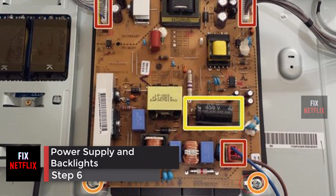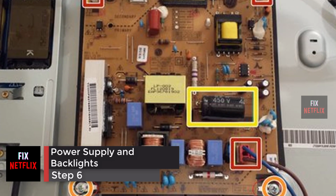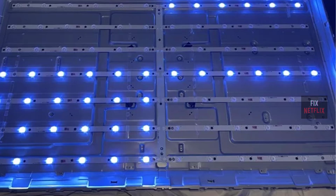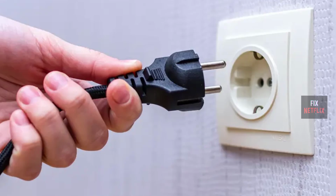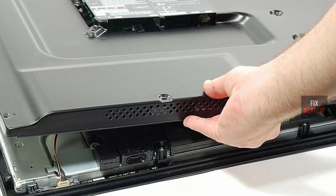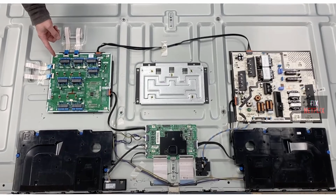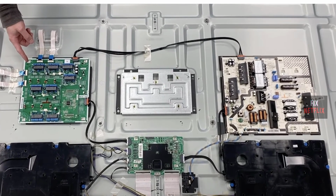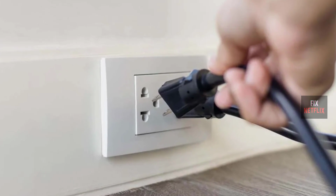Step 8. Power supply and backlights. You can check the power supply and the backlights in one swipe. Make sure the TV is unplugged. Open the back. You may need to remove the base to access all the screws that hold the back on. Disconnect the black cable between the main board and the power supply board. Plug the TV back in.